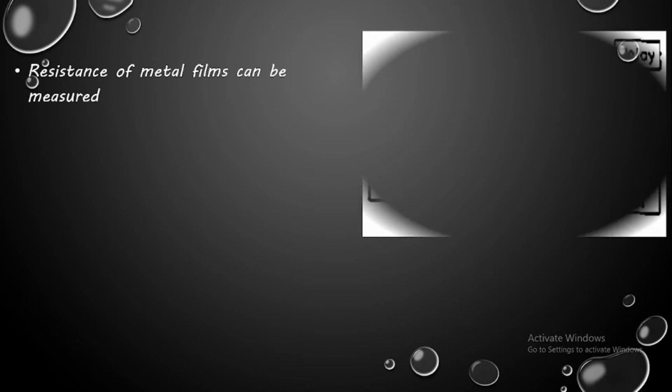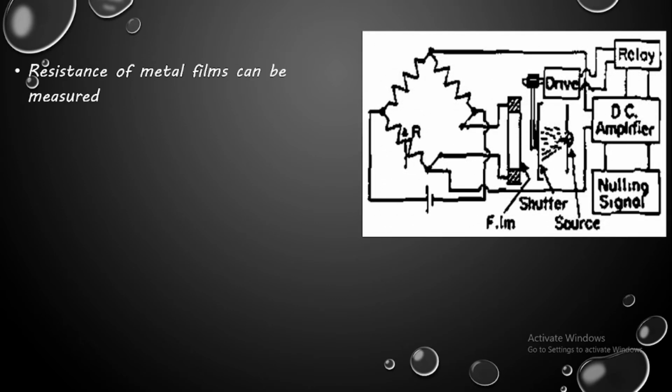So let us understand how the calculation is done. The resistance of a metal film can be measured easily by making the film one arm of a DC or AC Wheatstone's bridge. Here we can observe a rough idea of how it works. We know the Wheatstone's bridge is helpful in determining an unknown resistance: three out of four resistances are known, and by the Wheatstone's balancing condition, which is in the form of ratios, we can find the other unknown resistance.